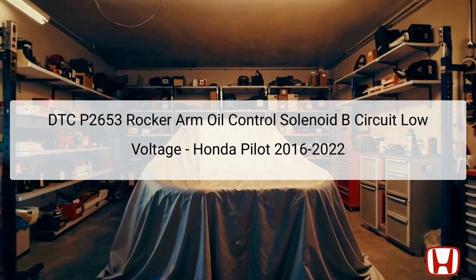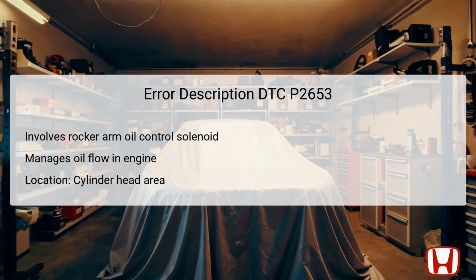not addressed. The solenoid is usually located in the cylinder head, connected to the engine control module, ECM, via a 2P connector. Accurate diagnostic action is essential to resolve this issue to ensure the performance of the Honda Pilot remains optimal. The DTC P2653 indicates a problem with the rocker arm oil control solenoid B circuit for Bank 1, showing